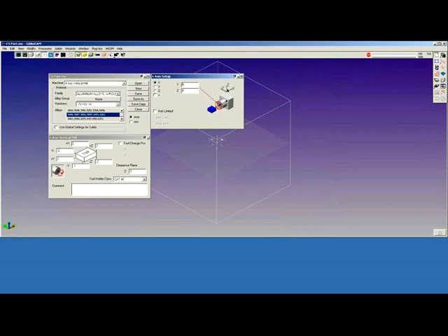The axis markers show the positive direction of each axis: X positive to the right, Y positive away from the operator, Z positive upwards. The red arrow indicates the clockwise rotation of the rotary axis, and the Y and Z dialogues determine the center of rotation on this particular setup.